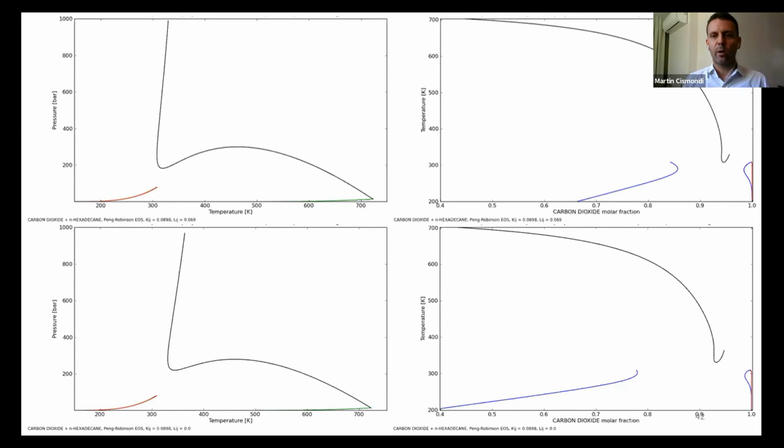They did very nice work, but CO2 hexadecane or CO2 alkanes are not easy to model with standard mixing rules, like in this case. So you cannot have everything at once with the same parameters. But what you experienced is something very common when working with these systems. The behavior and the envelopes, especially critical conditions, are very sensitive to binary interaction parameters.